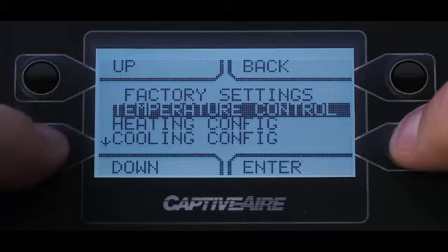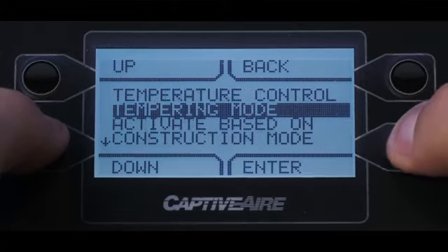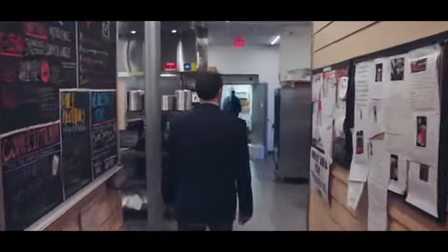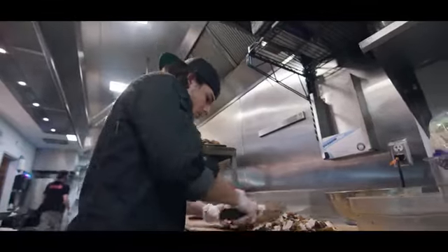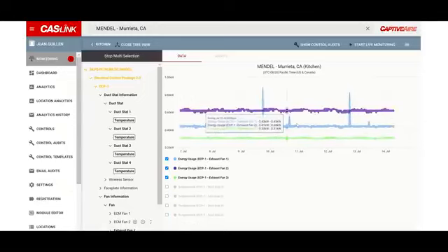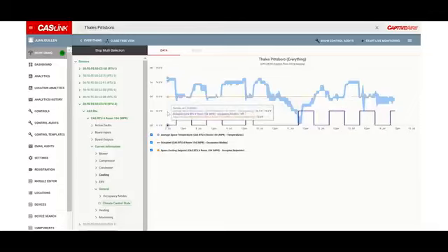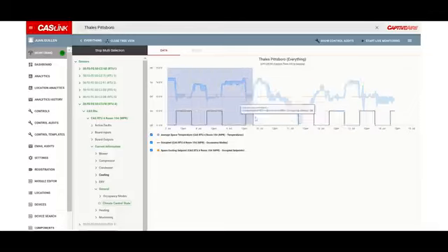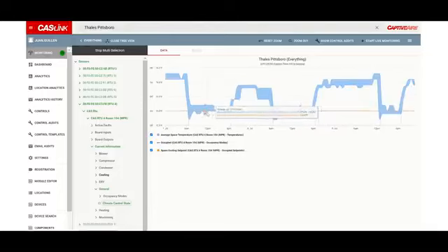There is no guarantee that the equipment will operate as it was intended to once you pass it on to the end user. If at some point settings are changed or something was not set up properly right after the building was turned over, then there's a risk that those units will potentially operate 24/7, operate at times where there's no one in the building. So a building management system takes away those risks. It gives you visibility of what your different components are doing and making sure that they are not only operating efficiently, but also operating only at the times that they need to be working. So it all comes down to energy and comfort in a lot of cases.